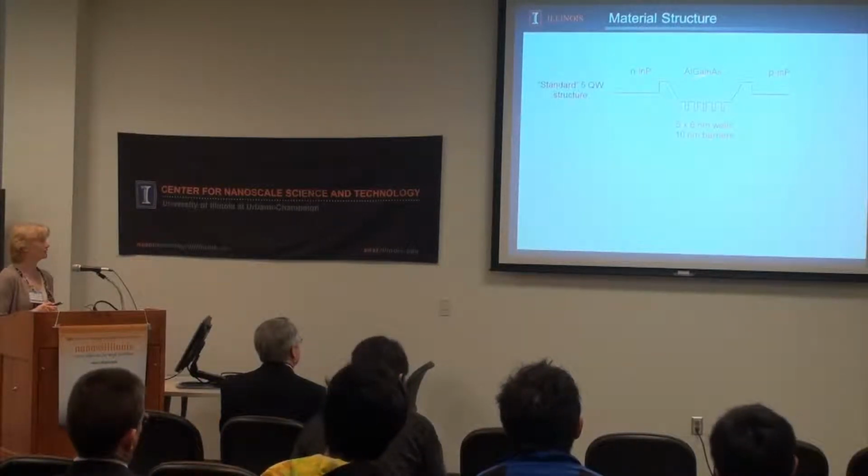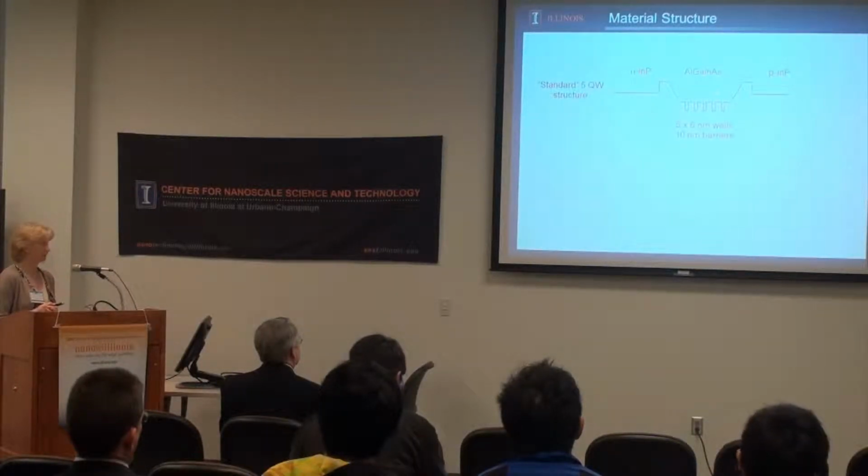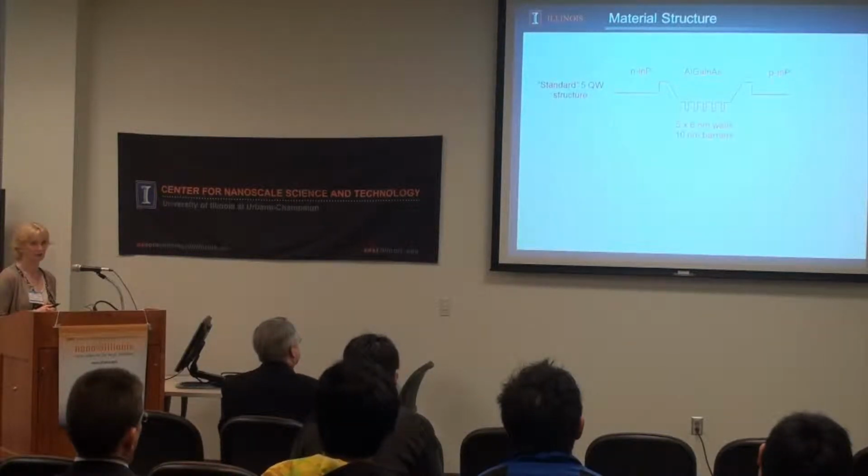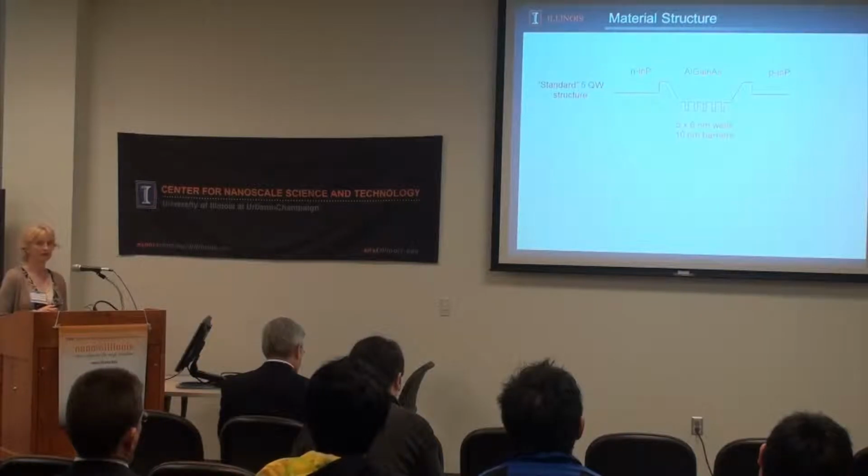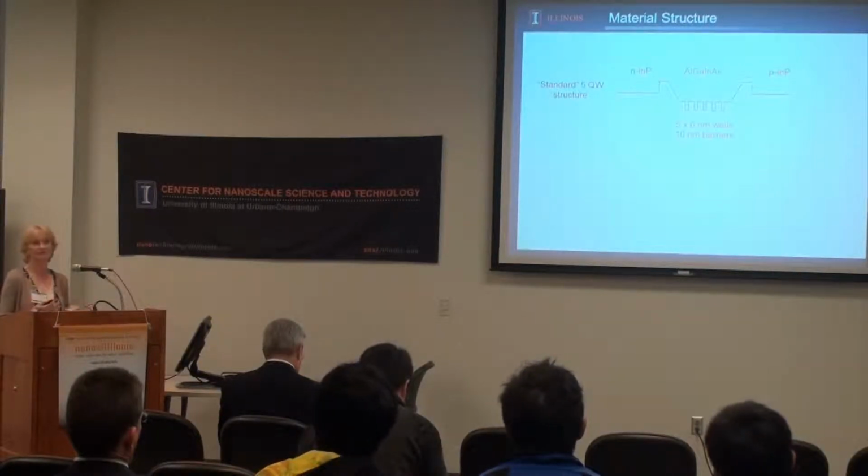We have both the electrical confinement and the optical confinement. With this smaller band gap, we have a higher refractive index, so this forms the waveguide too. Now, this is a traditional structure, which is basically what's used in the lasers used in optical communications for the transatlantic cables and any other situation.